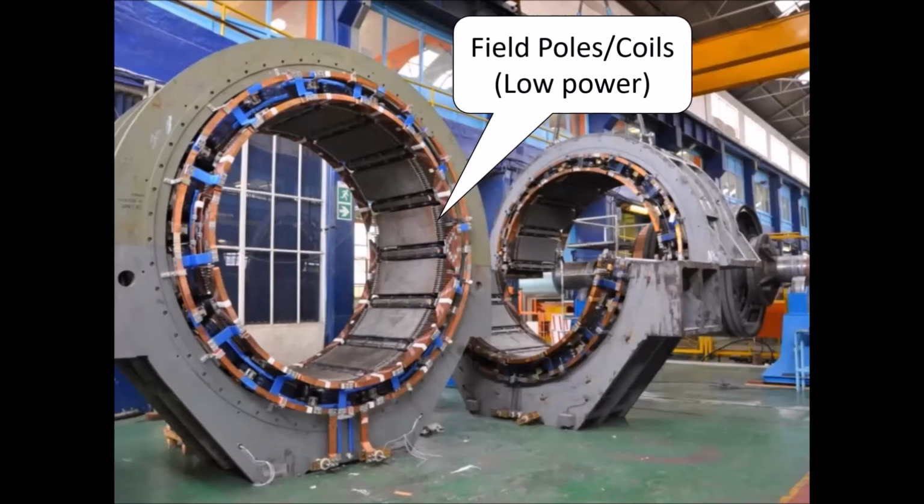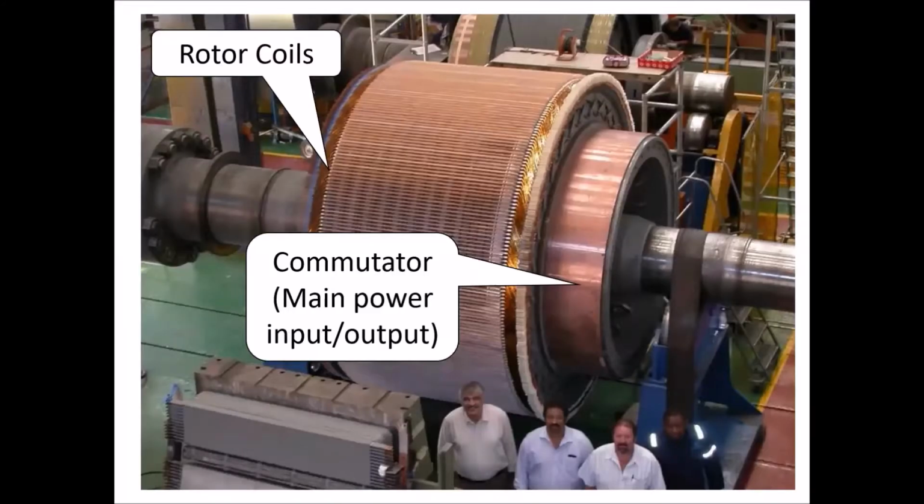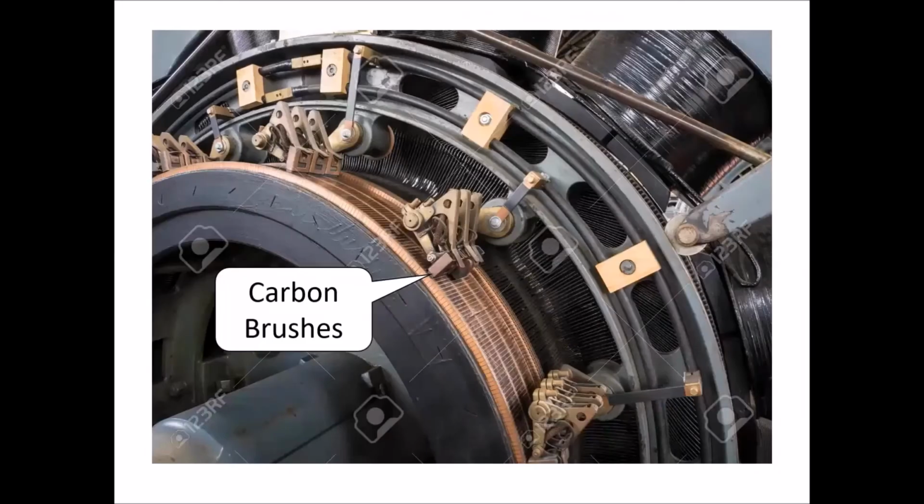The business end of the DC machine is the rotor bit with coils that you can't see and a commutator. Each coil is connected to a copper segment on there. And this is an expensive thing to make, as you can imagine from the look of that. In this kind of motor, the power actually is produced in the rotor, and so the rotor carries heavy currents and quite large voltages. And how do they get there, given it's going round? Well, they're fed in through things called carbon brushes that rest on that ring of copper segments. You can't see very well there.